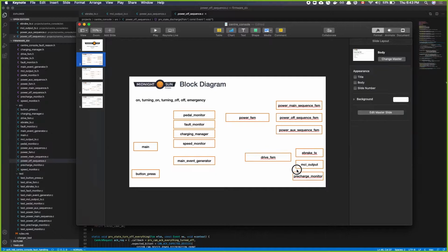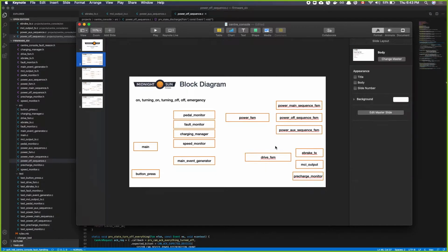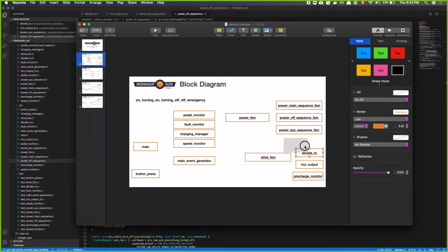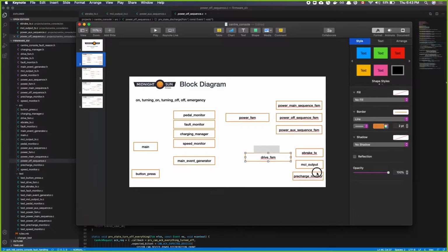Modifying this Drive FSM to ignore the eBrake is fairly easy. In that case, we would not really have a parking state. You would only have neutral, drive, and reverse, and your parking state would be when you're in neutral and the handbrake is applied. Kind of like a manual car. So that's pretty much as far as this Drive FSM goes.